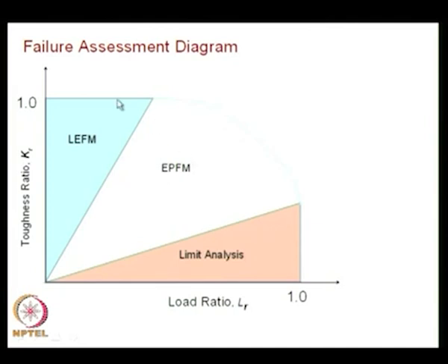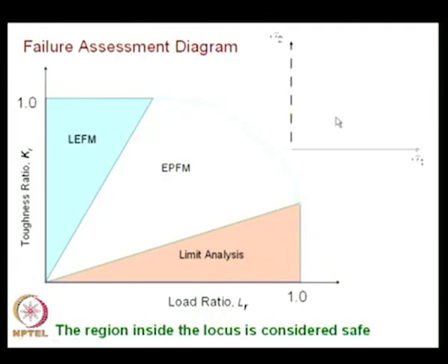See, what this graph says is, I can't have a straight line and another straight line meeting here. In conventional design, what have you done? You had combined loading of sigma 1 and sigma 2, and you say yielding occurs when sigma 1 equals sigma ys, or yielding occurs when sigma 2 equals sigma ys, and this is the yield locus you get from your Tresca yield criterion.